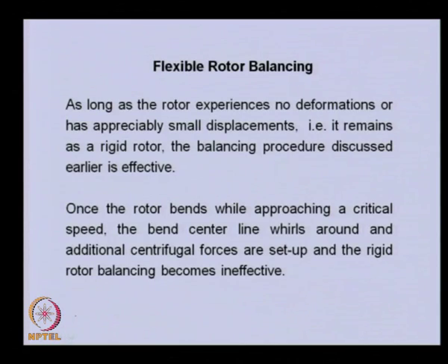When we are talking about flexible rotor balancing, we previously described the difference between the flexible rotor and the rigid rotor. Any long rotor, when it is not experiencing an appreciable amount of deformation, remains rigid, and the same rotor we can balance with whatever rigid rotor balancing method we discussed earlier.